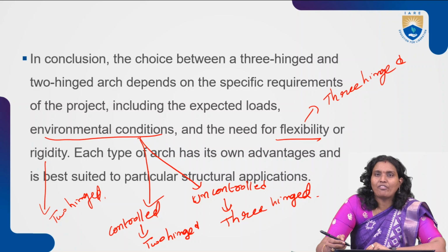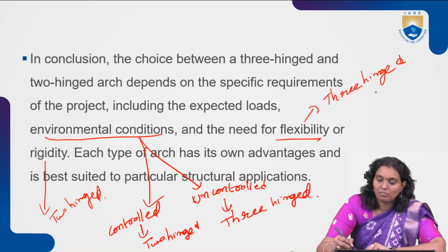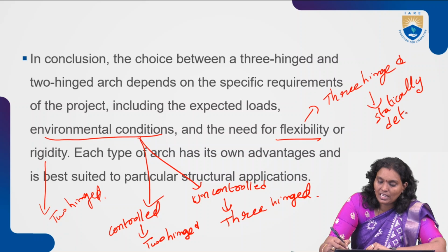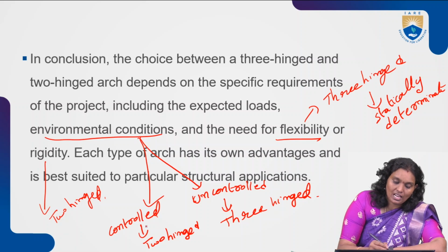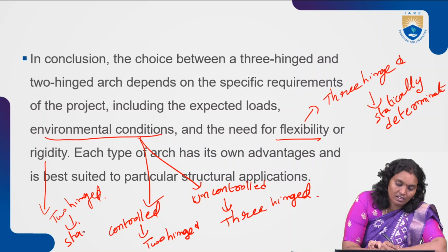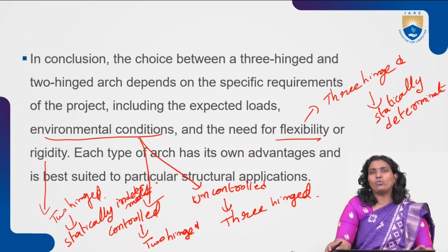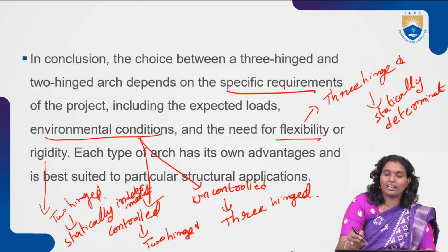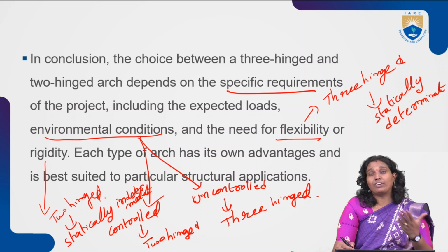So each type of arch has its own advantage. The three-hinged arch is statically determinate, and the two-hinged arch is statically indeterminate. So the overall conclusion is that it depends upon the specific requirements: what kind of internal forces there are, whether we require flexibility or rigidity.